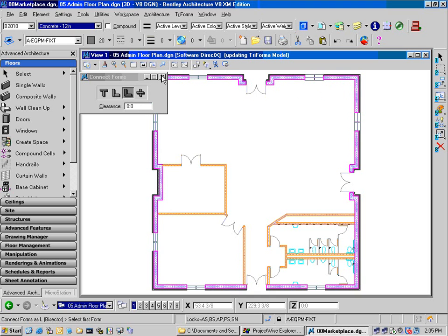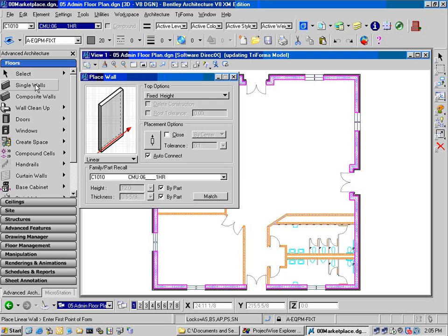Somebody sent me a drawing that just had, and I just used, say, the interior wall line as a shape, and I told it was a 12-inch wall thickness. I could just extrude that single line shape up into the wall height, right? Yes. Okay. Yep, exactly. When I place a wall or I extrude a wall, I can do it by the part definition. If I turn that switch off, the data group for this 1 hour rated 6-inch CMU block wall, its default height is 12 feet. But I can override that and put it in at whatever height that I want.